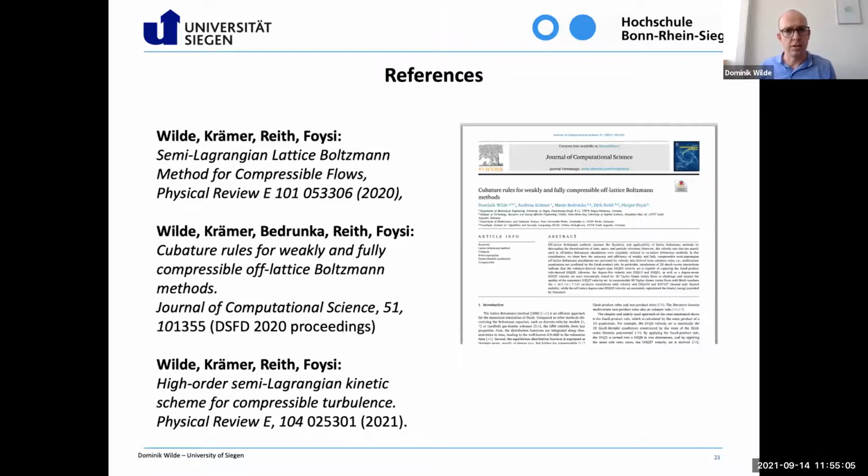And the other question is: is the dissipation induced by the interpolation? Well, yes, there is definitely a sort of dissipation, but you can decrease the viscosity which is introduced by the dissipation which is introduced by using high order interpolation polynomials.